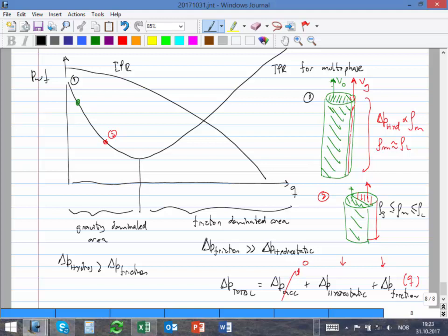In this one, I think I made a mistake. It should be very small the velocity of the oil, and very big the velocity of the gas. And here they are more or less the same. So that's what happens when you increase the velocity. The oil starts to go quicker, and then the gas can catch up with it. When the oil goes very slow, the gas just drops it: you go too slow, I will go at my pace. A kind of simplistic explanation.